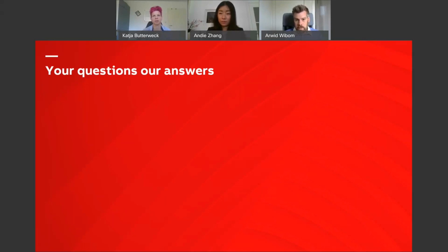We have a question from a Yumi programmer in a mechanical factory. When you change the reading height of the item, is it necessary to change the focus of the Yumi's integrated camera? Yes, if you're too far away, you need to adjust the focus.